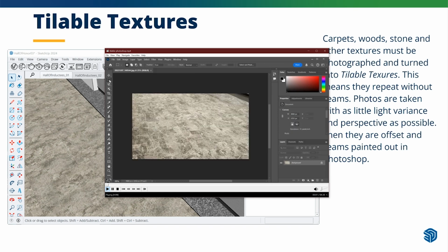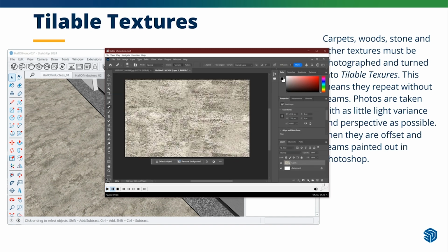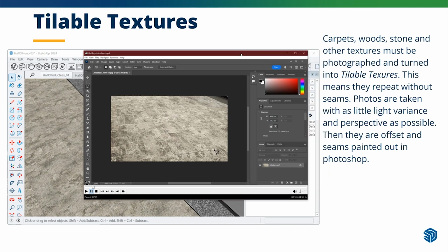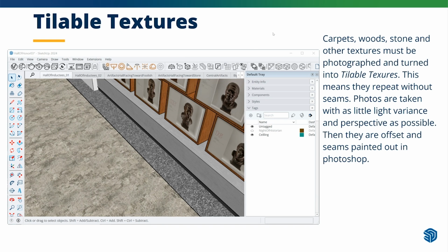So you often have to kind of dull it out so that the pattern isn't so prominent, or choose to sample a larger piece of carpet so that you have a 10-foot by 20-foot swatch, for example, and you'll get better results. They don't necessarily need to be really high res, which takes up a lot of memory and possibly, again, is a burden on that old laptop that may be getting used.